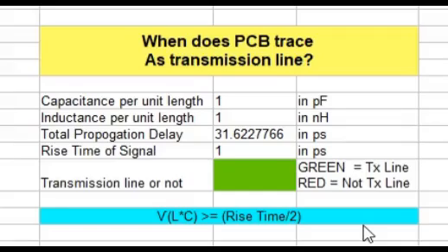Okay, now the first question comes to the designer. How can I know inductance per unit length or capacitance per unit length? So this is actually known over a period of time, and then how much width you are routing the trace, how much long you are routing the trace. Based on that, you can come up with the L and C values. Like this is a very typical thing. Okay, and this is only known by experience,